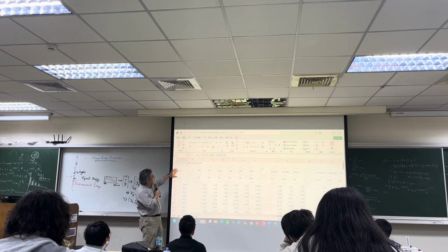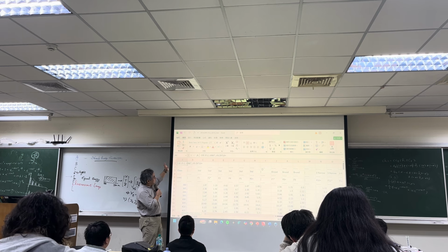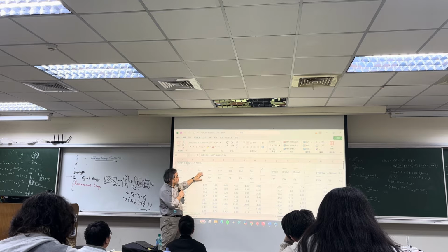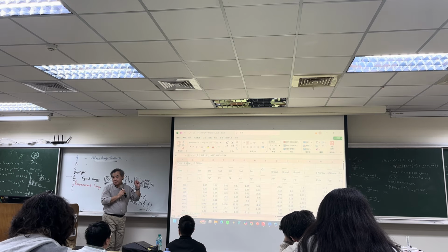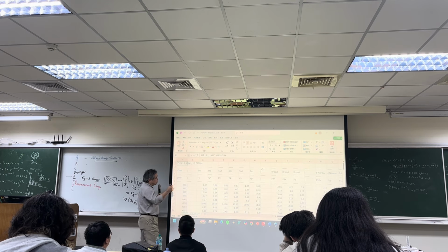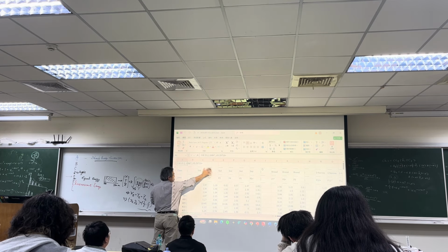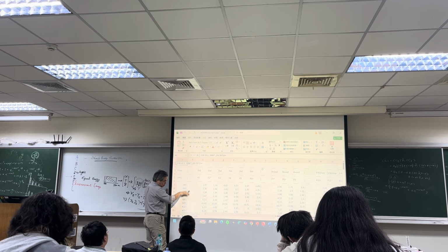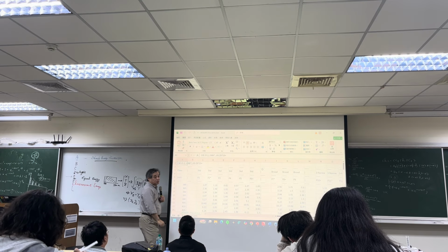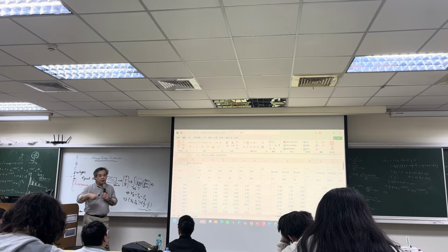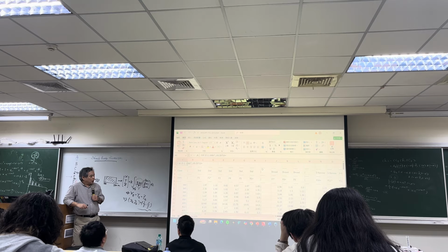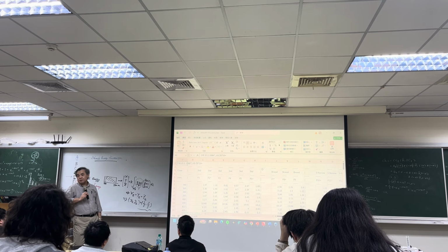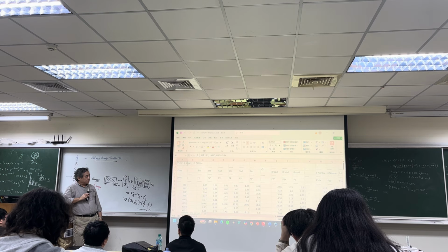You must take care of the measurement condition, the measurement quantity, the name, and the unit, or some scale. You must record all the details at the beginning, then start recording the measurement numbers. Otherwise, after 1 month or 3 months, nobody knows what the numbers are. Okay.